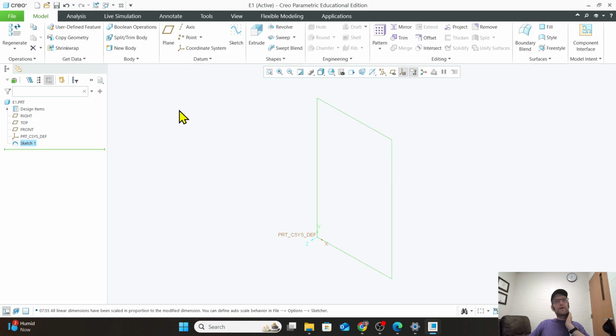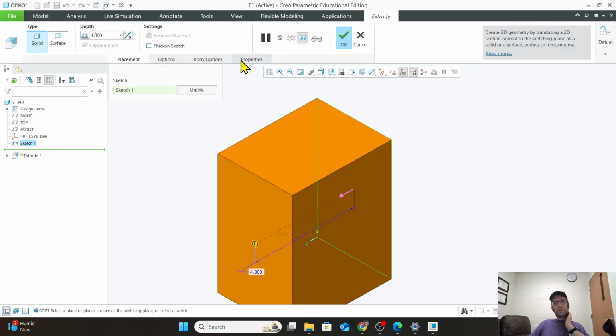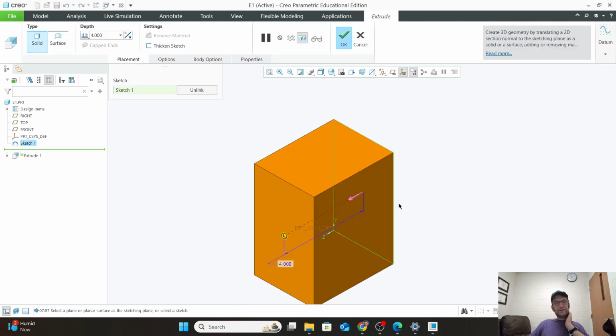Okay. We're going to choose this extrude option right up here. By default, extruding will allow you to pull a sketch into the third dimension or push it and bring it into that third dimension. We're going to extrude this guy and bring it out and set the depth of that to 1/2 inch, which we can do one of a couple ways.